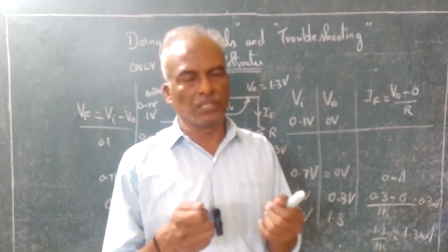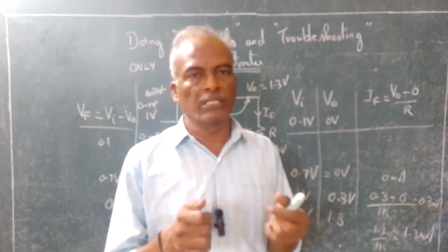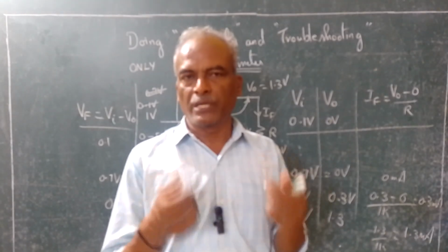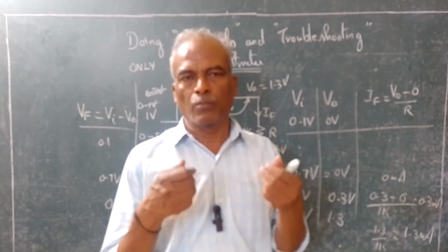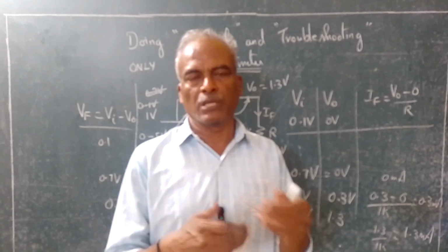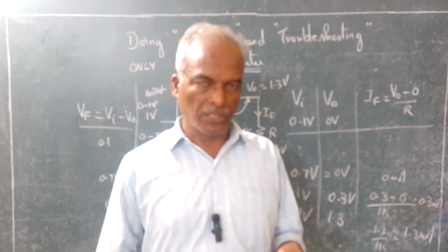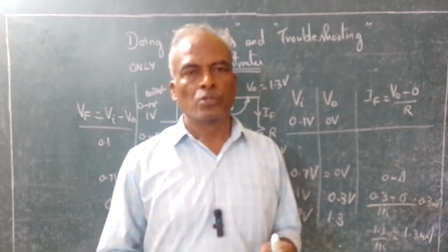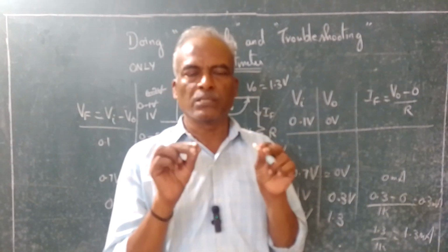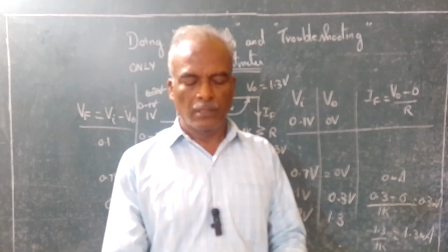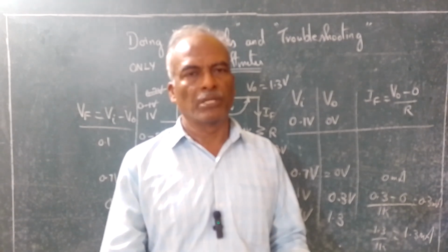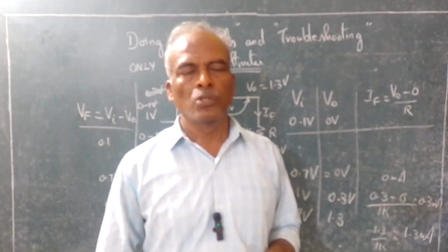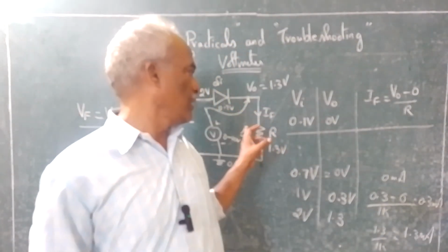When you measure the resistance, see that your hands are not touching the component, because if you touch both the ends, your body resistance between these 2 points will come in parallel with that resistance, so it is likely to modify the resistance value. So touch the insulated parts of the wire and then touch the component and measure the value. That will give you a fairly accurate value, and that value you can write down here.